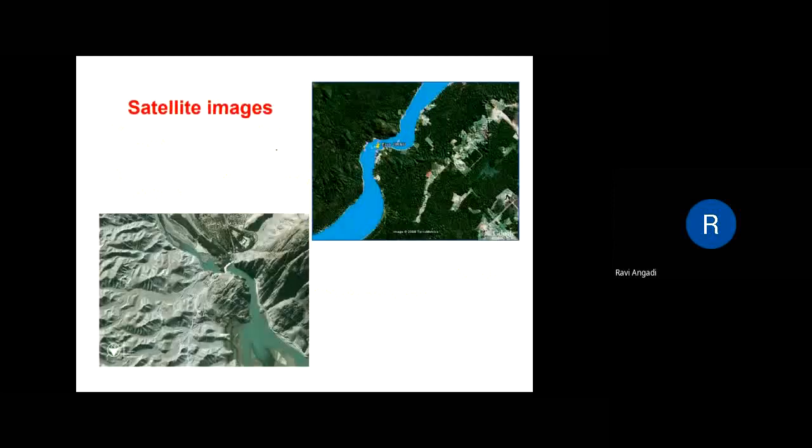And the geotechnical engineer should also get the information about the type of structure to be built and its proposed use. In the case of multi-story buildings, the information about the column loads and their approximate location should also be obtained. And in case bridges are proposed, the span length and the load carried by the piers and abutments should be taken into account.